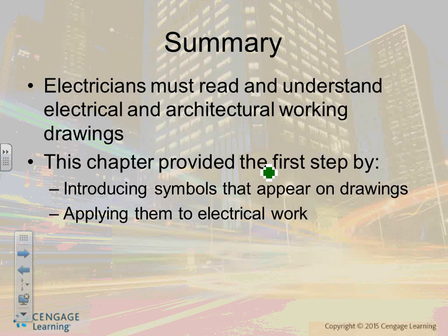If you guys look at page 41, switches, look at all the symbols, the dollars. Are you the one who asked me about the dollar sign? Yeah. The dollar sign or S. There are two ways. Either you put S or a dollar sign. So either single pole switch, you're looking at them right there, the same single pole switch is there. And then right underneath, if you put 3, that will be a 3-way switch. If you put 2, double pole switch.